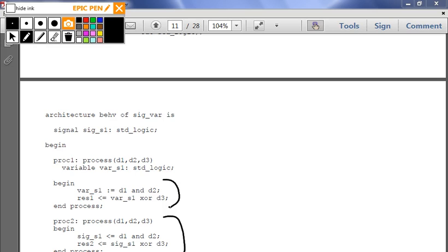So we made the second signal, where signal buff is mapped to input 3 after 5 nanoseconds, and it matched. The result was a 10-nanosecond delay, which is what we expected, because we have 5 nanoseconds of buffering from the AND gate and the buffer, and then the XOR, which was 5 nanoseconds calculating the output signal. So it was the exact same thing as the variable version, except with a 10 nanosecond delay, which is what we had coded into it.